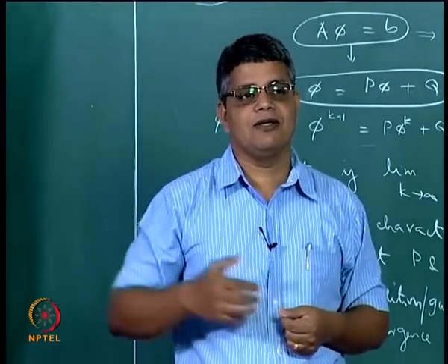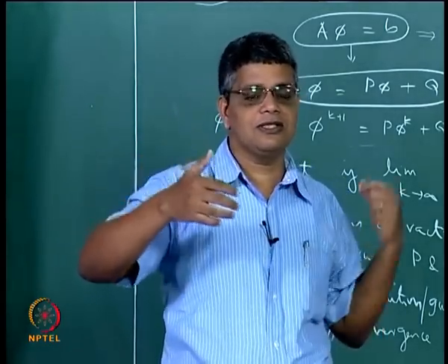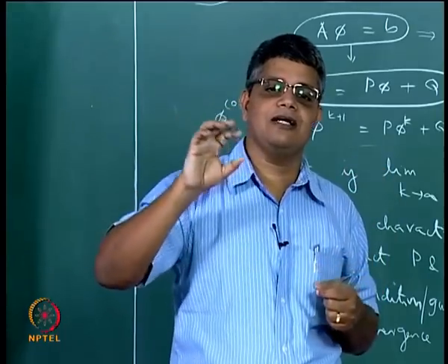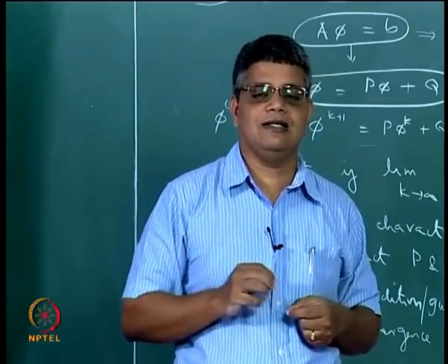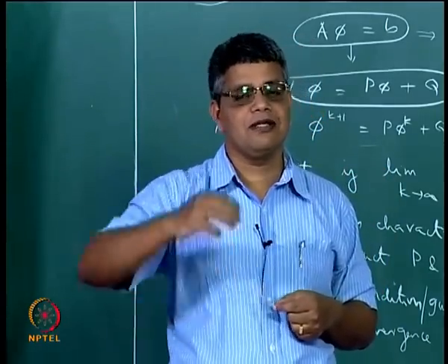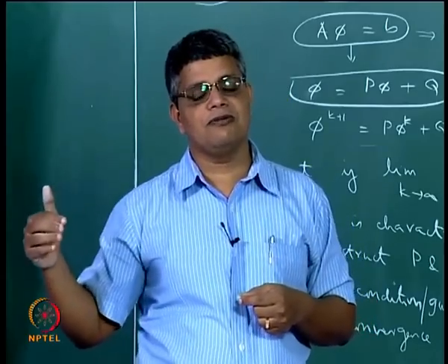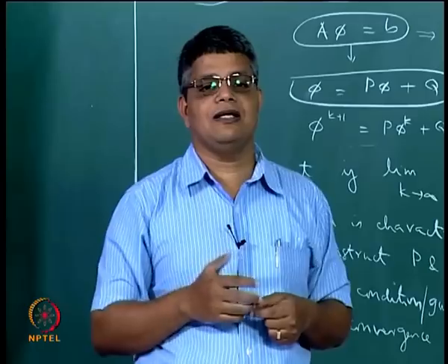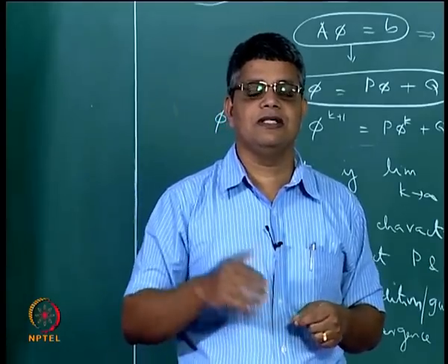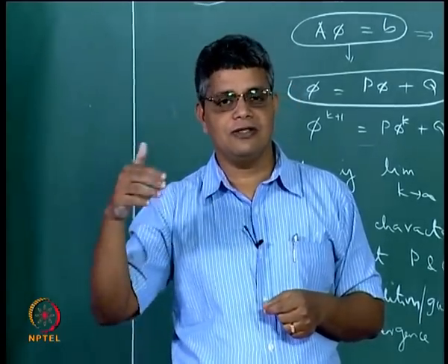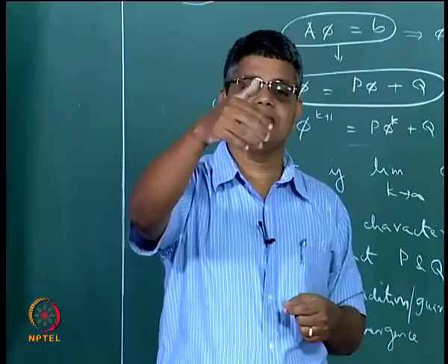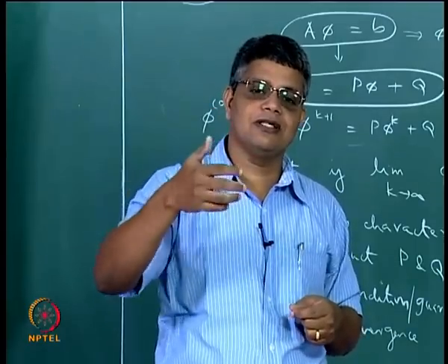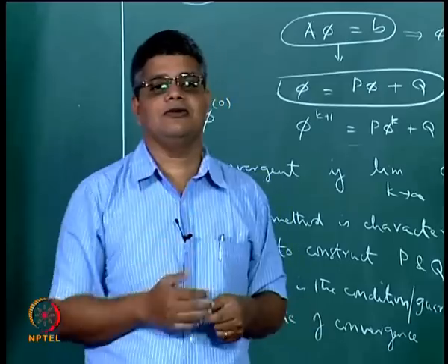momentum equation. So you solve the x momentum equation using the iterative method until you get to some reasonable improved solution. You go to the y momentum equation, solve for V, and then you solve it until reasonable improvement, you go to the W equation, and once you get this, then you can come back to the U momentum equation and then substitute the improved values for V and W and then go like that.